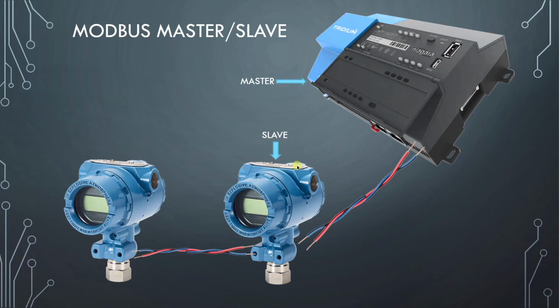How does Modbus communicate? It is basically a communication between two controllers where one acts as a master and another acts as a slave, and there can be a number of slaves down the line. If your controller is a master asking for certain data from this slave, it will send a request or a query to the slave, and the slave is going to give the master a response to the query. That's how the communication is.